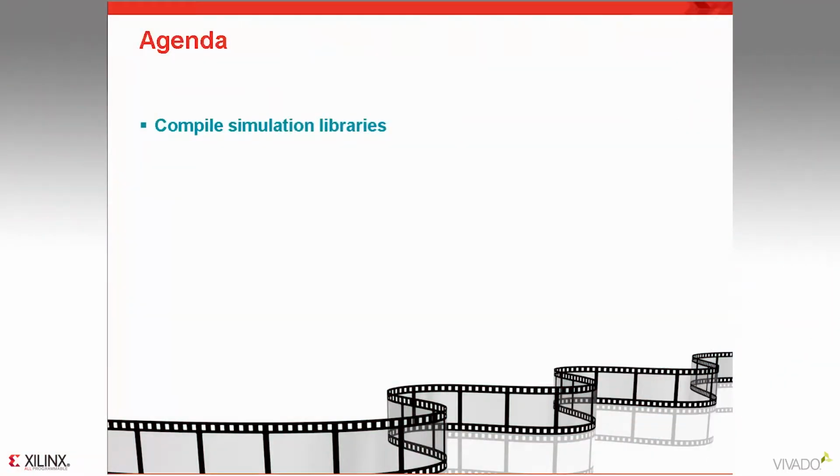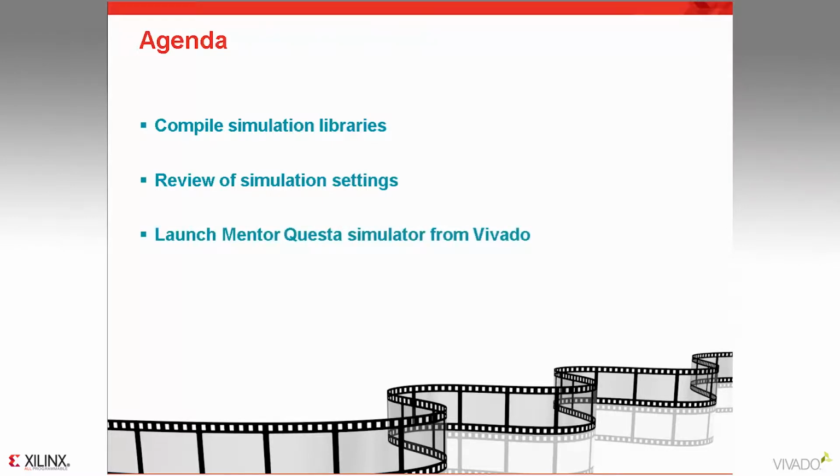We will start with a quick introduction to the concept of compiling simulation libraries and why you might want to do this. We will then look to see how you go about setting up the project with correct simulation settings in Xilinx Vivado Design Suite. Once we have finished setting up the simulation, we will look at how to launch Questa Simulator from Vivado.